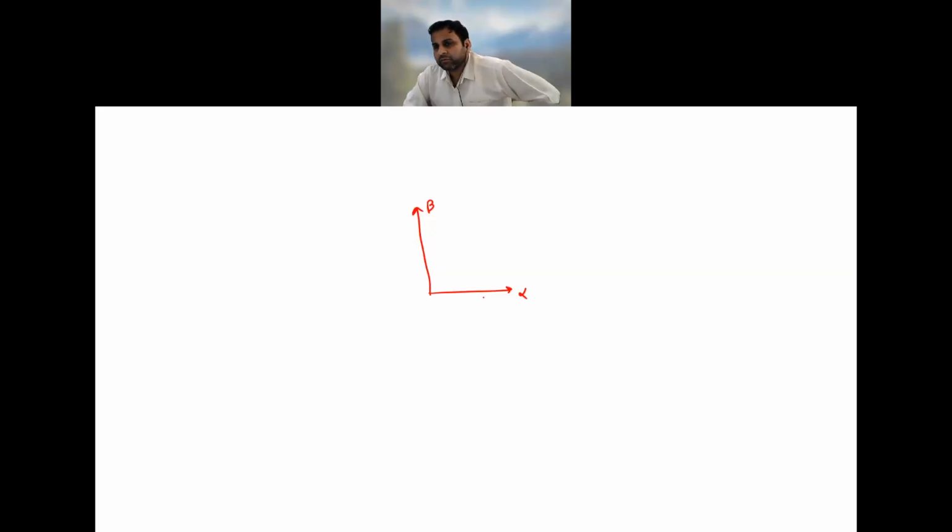Then you can take the magnitude, the square root of Vs alpha square plus Vs beta square, and that is what you will get as the magnitude of the vector. Once you know the magnitude and the angle, you can represent that particular vector. So we just want a 90-degree phase shift, or two axes displaced by 90 degrees. Why 90 degrees? They are independent of each other, and we always wanted to have a representative axis using which any vector in that plane can be represented. That is why we have defined 90-degree displaced vectors.